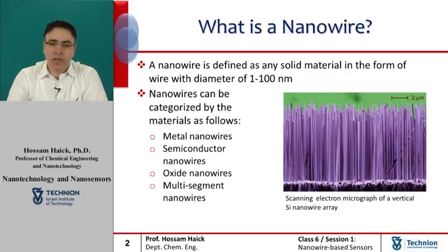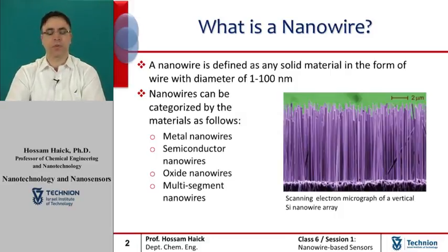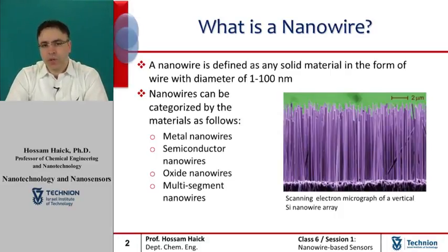Compared to other low-dimensional systems, nanowires have two quantum-confined directions, while still leaving one unconfined direction for electrical conduction. Basically, this allows the nanowires to be used in applications where electrical conduction, rather than tunneling transport, is required. Because of their unique density of electronic states, it's expected that these nanowires exhibit significantly different optical, electrical, and magnetic properties than their bulk counterparts.